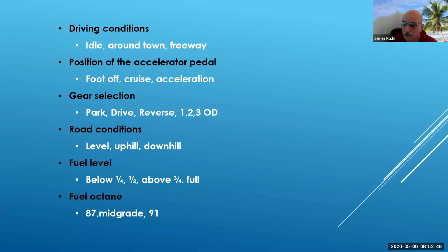And when you get down below that quarter point, you actually overheat the fuel pump. One, because one of the things that the fuel does is help cool the fuel pump, because it's an electrical device. And the other thing too is you get a little bit of starvation going on when it gets fairly low. Additionally, as much as they try to keep the fuel clean, these gas stations keep things clean.